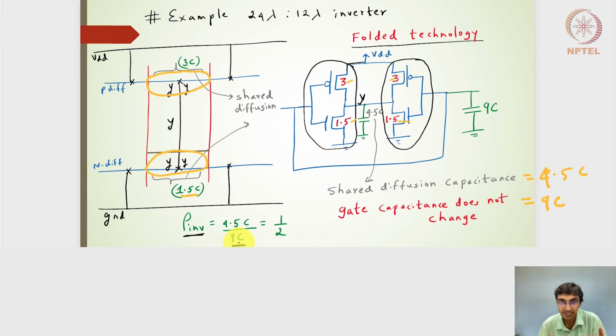In terms of the conventional design, if I consider the charging current and the discharging current coming from the VDD rail and going to the ground rail, the benchmark inverter will still be 6:3, because at the VDD the charging point, and at the ground rail the discharging point, the current going to the ground rail while it is coming down will still be 3i, and while it is charging from the VDD rail, it needs to still be 3i.